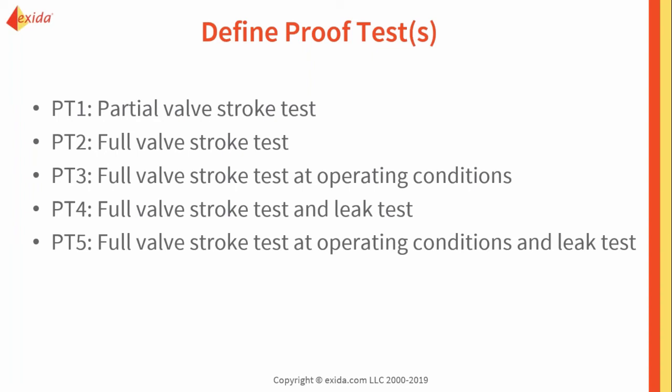And these might be things that you can even switch up and do both or multiples. I've seen people do that partial valve stroke test more often, maybe once every 6 months, where they do a full stroke test once every turnaround instead. And they know that their proof test effectiveness and the proof test coverage for each scenario would be different.